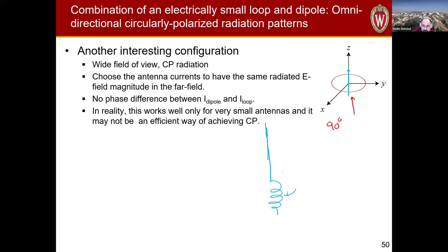But the purpose of this would be to resonate it out, because if you just have a monopole antenna, you essentially have some sort of an RC type network, and then with this inductor, you're adding your coil to reduce the feed point reactance of that, or even resonate that out.